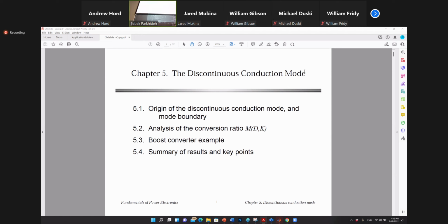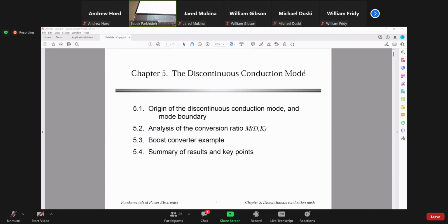There is a whole design process to guarantee that this doesn't happen. You can have it in your software, basically assuming that you do not have 100% of the switching period available. Or you can put hardware in to make sure that when one switch is on, the other doesn't turn on. In other words, in practice, when you have this dead time, which is needed, you engage this diode.